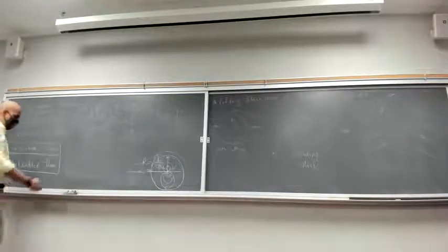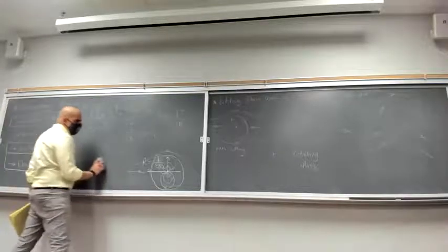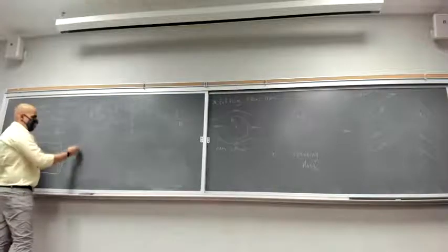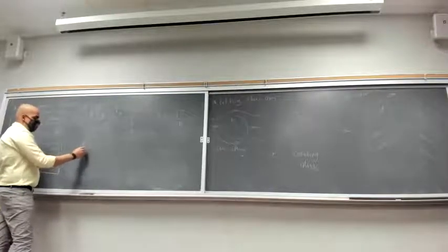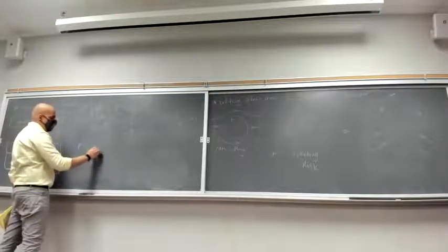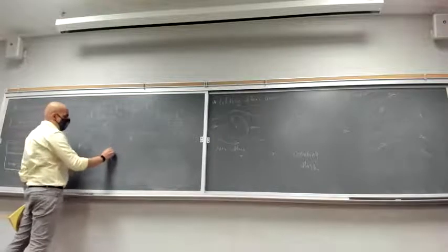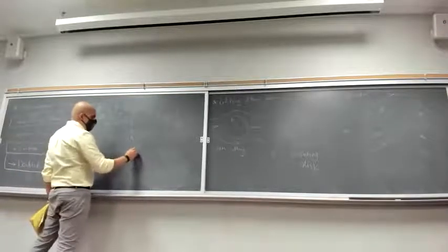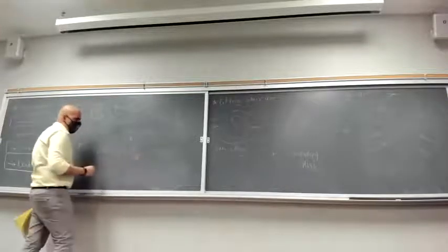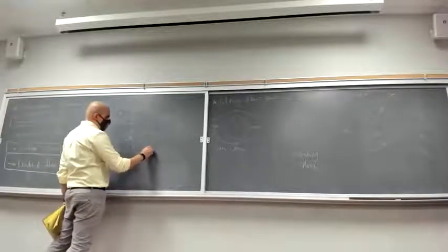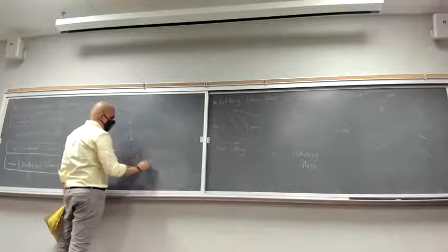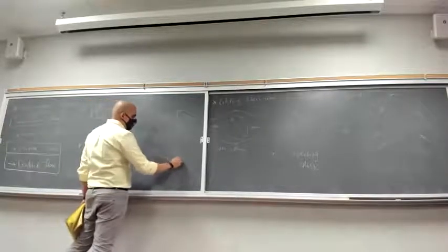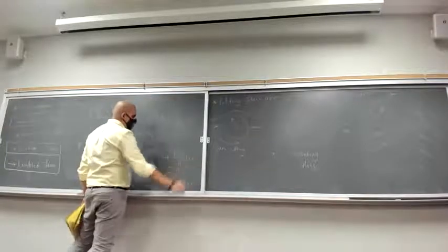Okay, so let's plug all of these values in. Psi of our flow here is going to be equal to v infinity r sine of theta minus kappa over 2 pi r sine of theta over r plus gamma over 2 pi natural log of r.